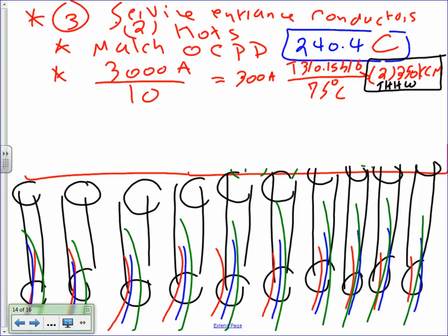Now, up to this point, we're done. We sized the overcurrent protection device, and we sized the panel, and we sized the feeders, the 2 hots. What's the only thing that's left? The neutral. Now here's what I can do. I can say, the heck with you, I'm going to use another conductor for the neutral and make 3 conductors, 350 each, and call it a day. Cool? So here's what some engineers do. They go, well, I'm going to have full neutral. They call it full neutral. And they carry, instead of 2 conductors, 3 conductors.